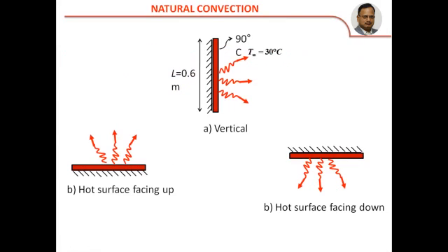Perhaps it is more appropriate here to concentrate and listen. Compare these two cases. Hot surface facing up: air molecules on the upper surface get heated up. Their density decreases because volume increases. Then buoyant force acts. They move up, and that place is occupied by another molecule.